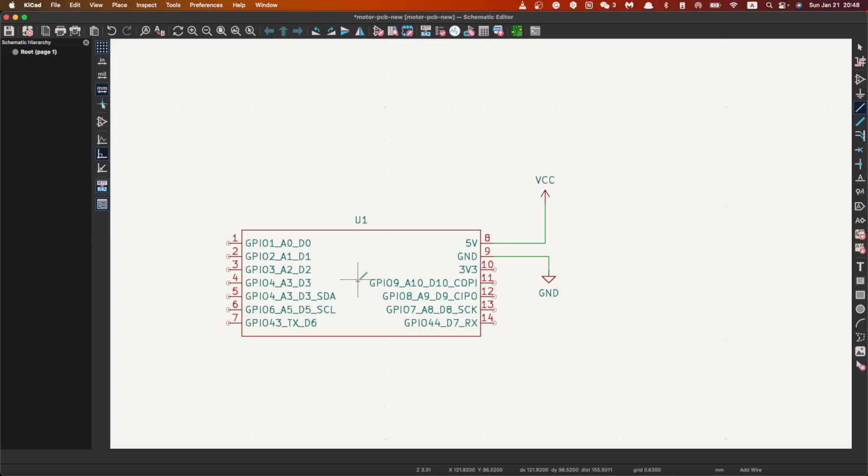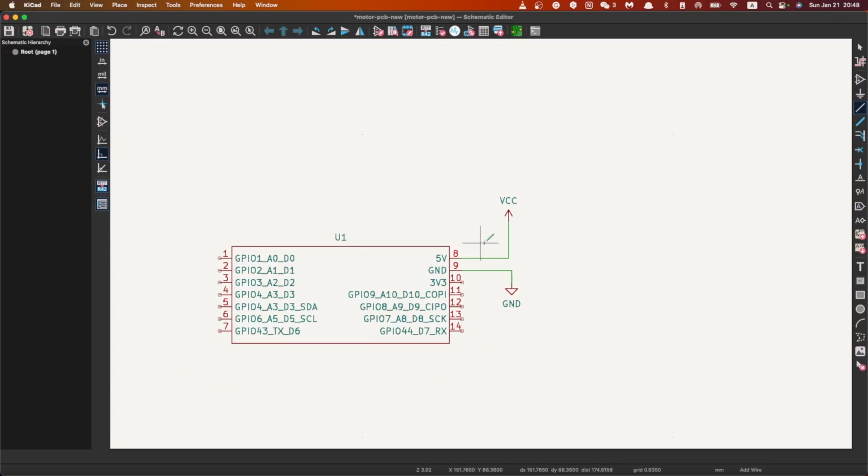The next thing we want to do is to have an LED there to show whether the board is being correctly powered. To do that, what we need is a circuit in parallel with the MCU, which means your board here. If the power is supplied, that LED will light up, and the MCU will be also working. And meanwhile, we also want a switch to be here so we can control the power of the MCU supply. So I'll switch back to my camera again.